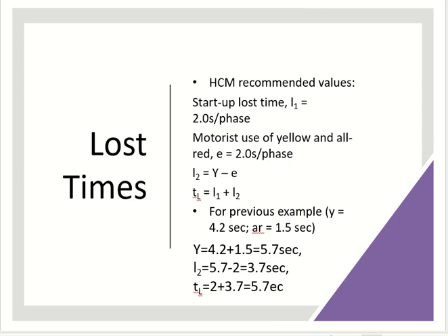Okay. The next thing which we need is lost time. Lost time is observed from the field. There are studies done to find out the lost time. We have discussed it earlier, I believe it was part of the previous section. You need to perform a field study to find out the actual lost time. But obviously, every single design may not give you enough opportunity to do these studies. So there are some recommended values given here.